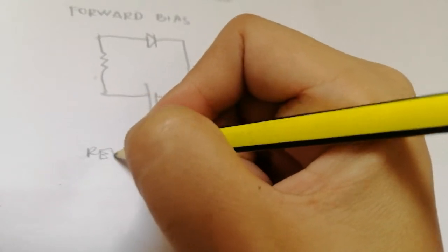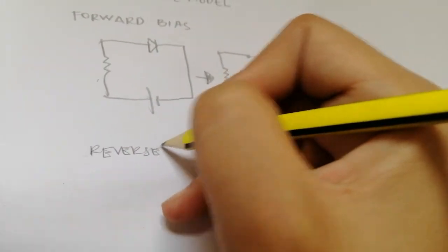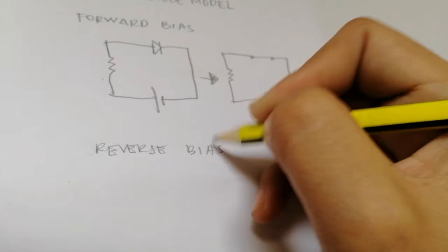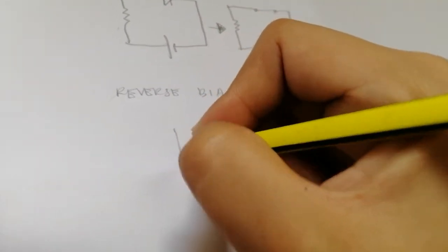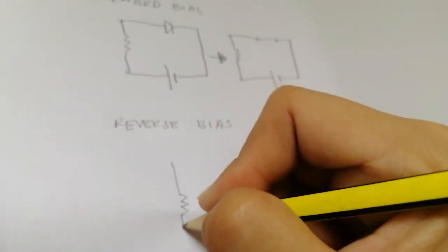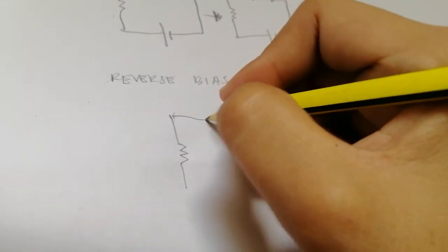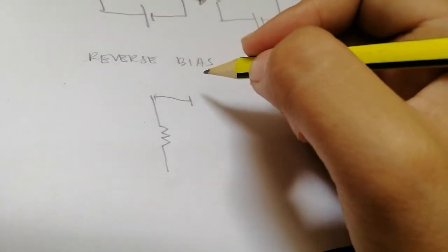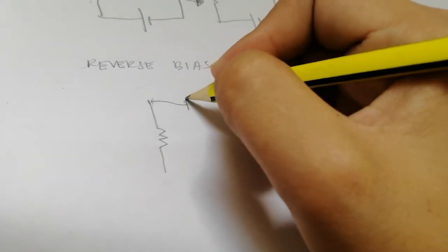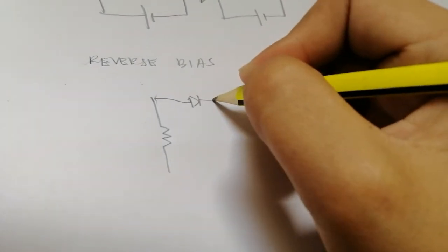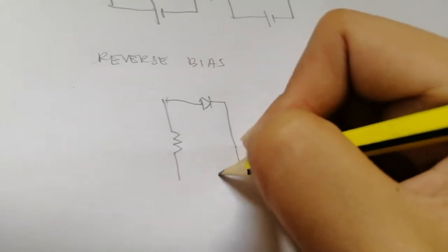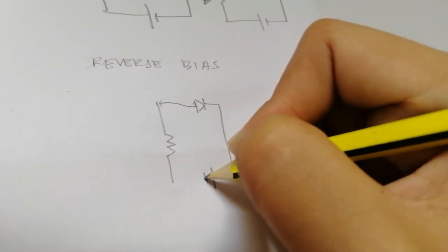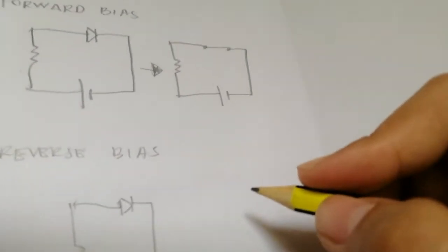Reverse bias is the condition that essentially prevents current through the diode. A DC voltage source is connected across a diode in the direction to produce reverse bias. The positive side of V bias is connected to the N region of the diode and the negative side is connected to the P region. Also note that the depletion region is shown much wider than in forward bias or equilibrium. The positive side of the bias voltage source pulls the free electrons away from the PN junction.